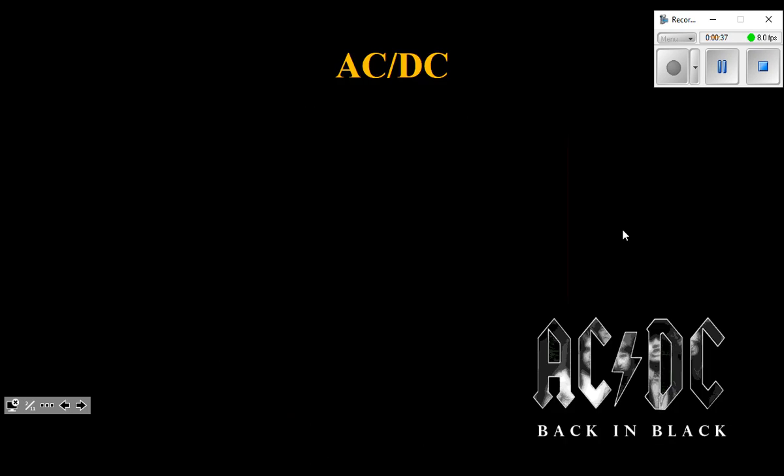So transformers. I'm going to start off talking a little bit about AC current and DC current. AC stands for alternating current, DC for direct current. And exactly what are they and what do they mean? Well, alternating current, much like the name says, the electron flow changes direction. So the electrons will start off at rest, speed up to a maximum speed, slow down, stop, turn around, go back up to a maximum speed, slow down, stop, turn around, and so on, back and forth, back and forth. And in North America, our current does that 60 times a second. So in effect, our standard light bulb is going to blink on and off 60 times every second.